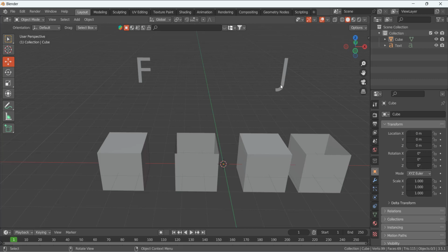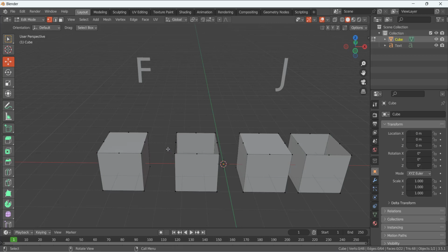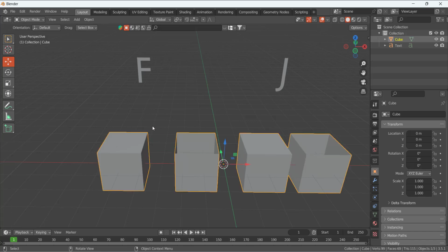And if you selected two vertices and there is an existing face and you connect them, it will cut through that mesh, like that face. So we are going to experiment with this comparison here. I added these four cubes here, so I'm going to press Tab to go to the edit mode. And here you can see that these are simple boxes. For this one, I just deleted the top face, and for this one, these edges, I just subdivided them.